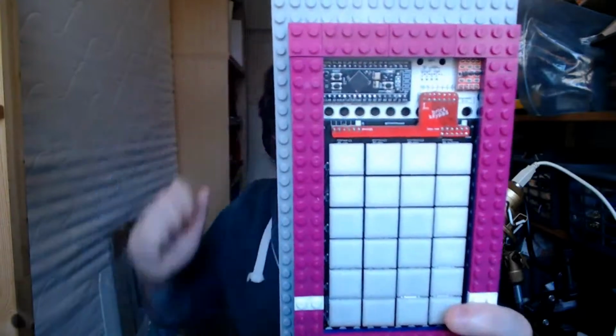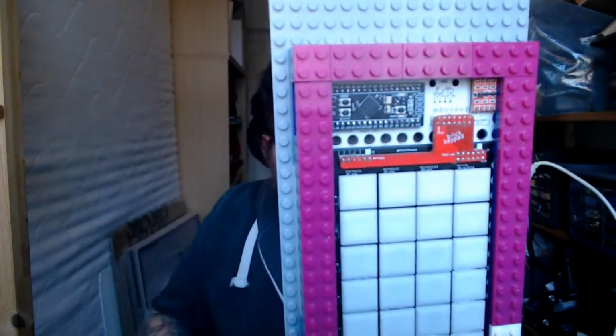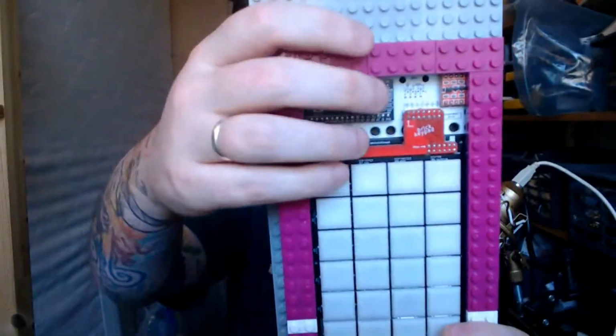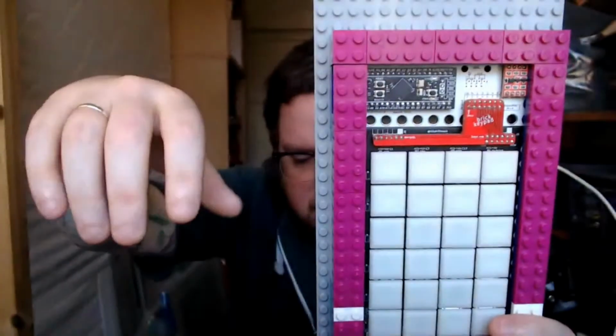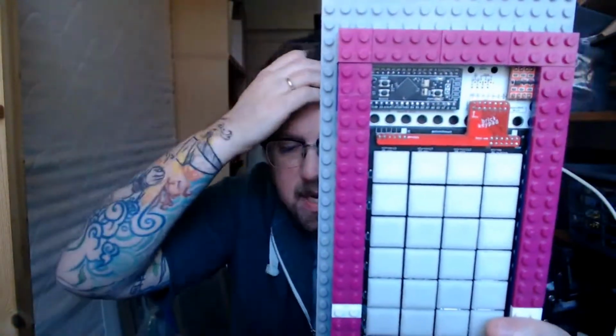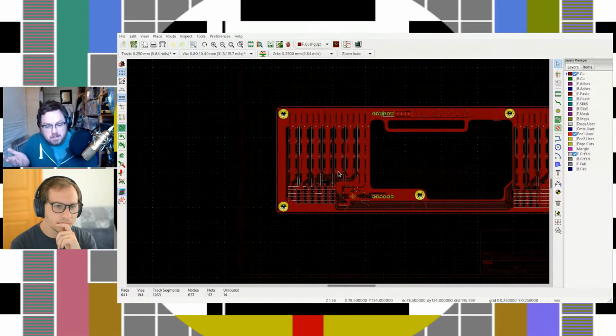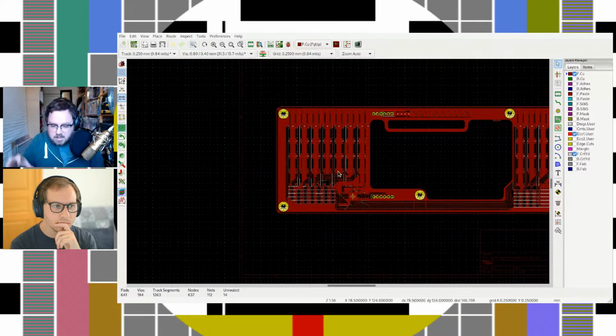You can buy a board that's been manufactured and does work for like 5-volt control and talking over USB and connecting and things like that. And that way you can just build much simpler modules, either in one or in multiple steps, where you can just keep the complicated stuff as an encapsulated module, and keep down the amount of complication you have to deal with. So this works really well for the microcontroller, where you may not want to hand solder all of the clocks and the capacitors, especially if they're very tiny components or have a lot of pins on them. And sometimes it's just cheaper and easier to get something bigger if you're not really hurting for space.